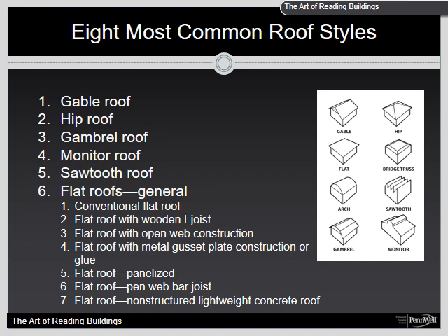Hazards. As with most lightweight construction, the hazards of this roof are numerous. It is basically constructed under compression and tension with sheeting in plywood or OSB. These components offer minimal resistance to fire. The chord members are exposed in the interiors of some structures, increasing the exposure hazard to the roof. Unlike conventional construction, the open space between the top and bottom chords will promote lateral extension of fire, resulting in early collapse of the roof.